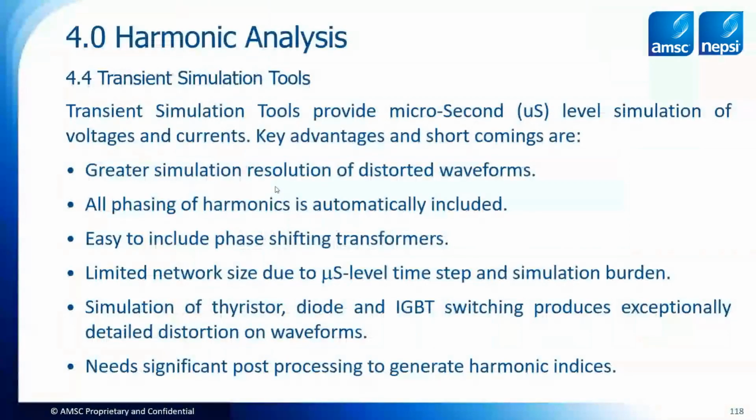So what about transient simulator tools? Now, if you ever plan on using these, you're going to be getting microsecond level simulation results. The key advantages are you get all this detail that you may not have had in the typical nodal analysis that we use for AC systems. All the phasing is included for transformers and loads and harmonics.